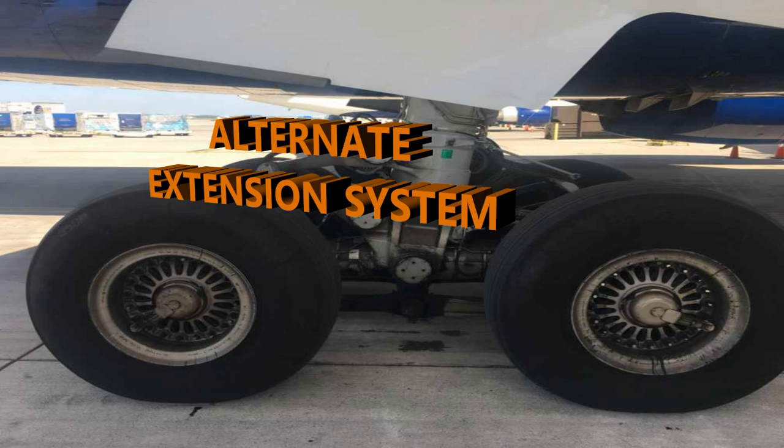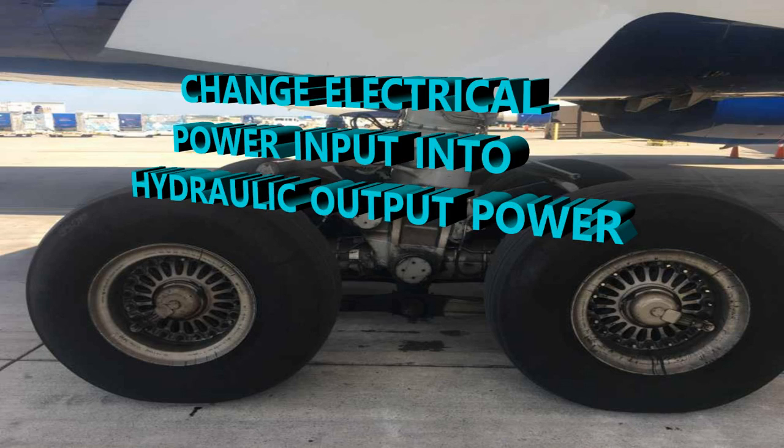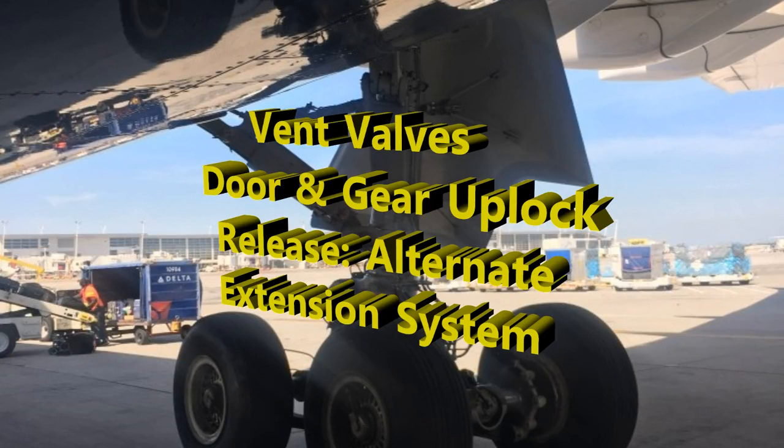The alternate extension is just that; maybe there's not a hydraulic supply getting through or something like that. You have alternate power packs that are part of the alternate extension system. So 2 alternate power packs, those are converting electrical input power to hydraulic output power. And then what other components do we have with the alternate extension system? Well, we have vent valves, because we don't want to have a hydraulic lock in that scenario. So there are vent valves, and then the door and gear up lock release. Okay, that's part of it.